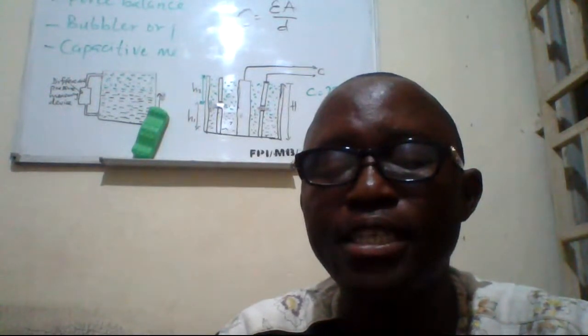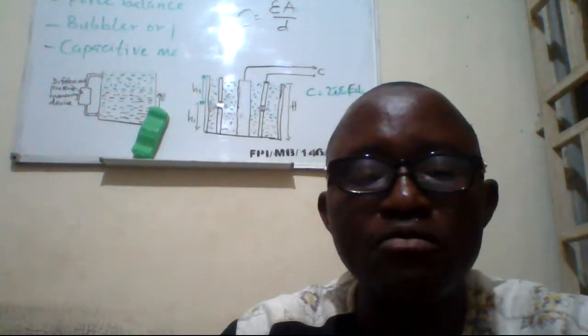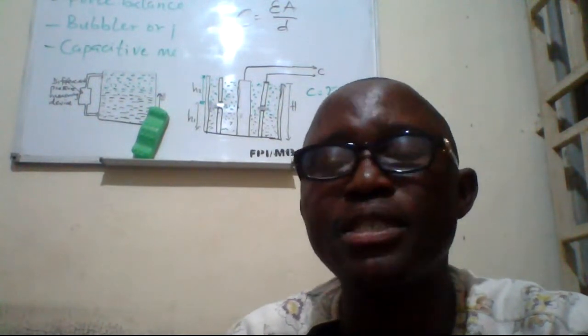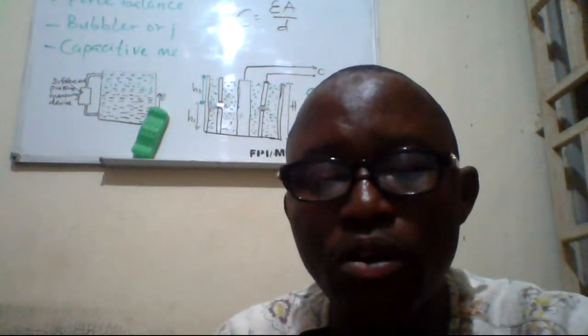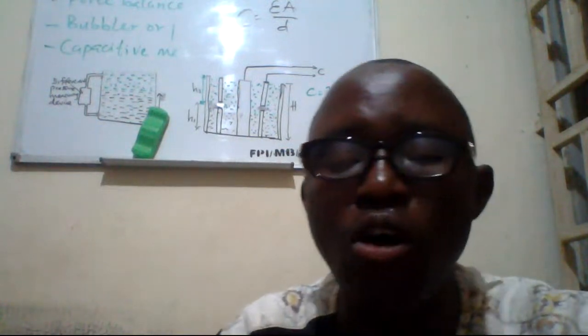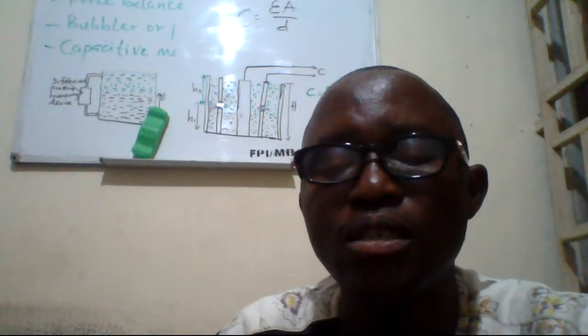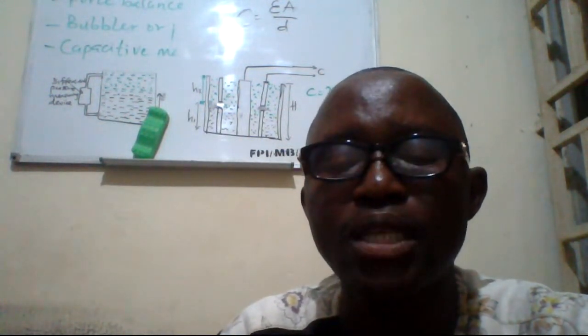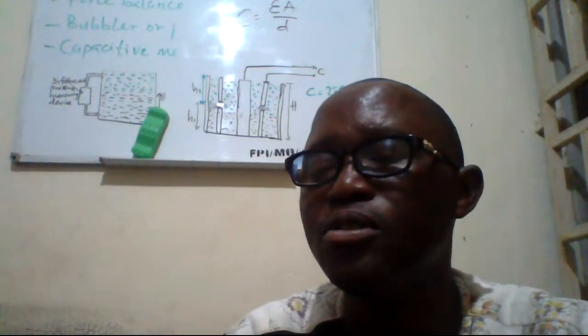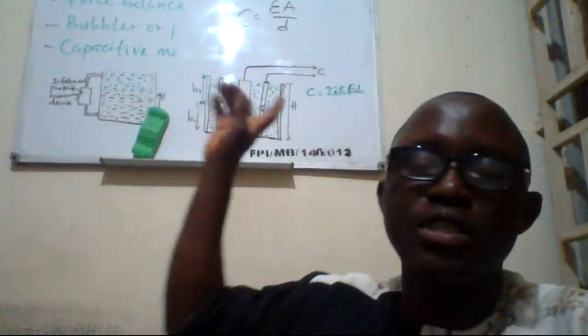All right. So that is the capacitive method. By determining the final capacitance, the equivalent capacitance thus formed between the fluid and the vapor, then using this formula, the height of the liquid can be determined. And then there is a calculation also on the system based on this same formula.